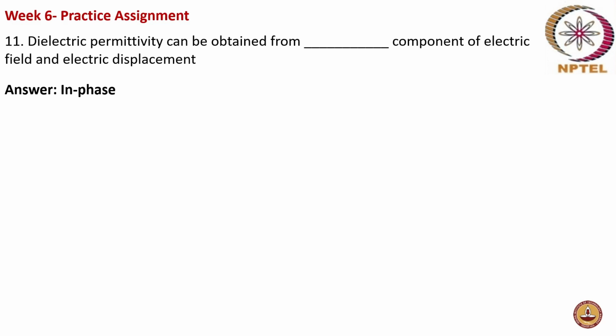Okay. So for polymeric materials or viscoelastic materials, it is actually the complex permittivity. So it will have a real component and an imaginary component, where the real component says the dielectric permittivity or the capacitive behavior, or how it stores the electric energy, whereas the out of phase component says the dielectric losses. Okay.